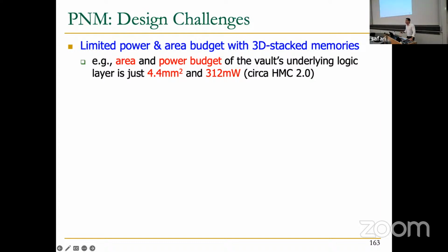So when you are designing a memory chip and you're going to embed logic inside that memory chip, you need to always remember that your memory chip initially is not there for computation. It's there for storing bits, for density. And once you start messing with that, you are decreasing the memory density of your chip. And it might look like a red herring: okay, maybe I don't care about density.